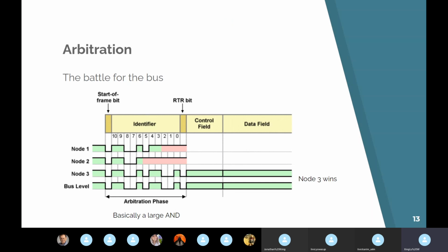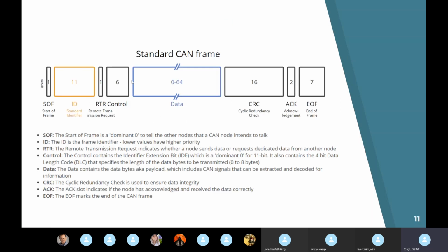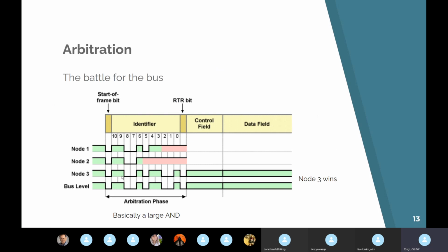And then everyone goes through, and basically the whole bus is showing the whole CAN frame. And when this is completely finished, then the next 2 people can put up their poster. So person 2 would put up the poster next because they're higher priority than person 3. But once the poster is put up, everyone sees it, and no one can send any messages while it's up there. So no one can just interrupt them halfway through the message.